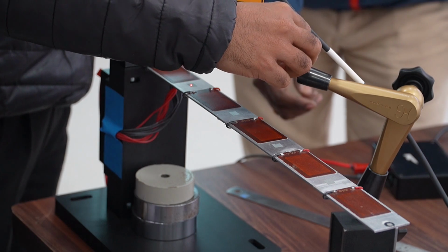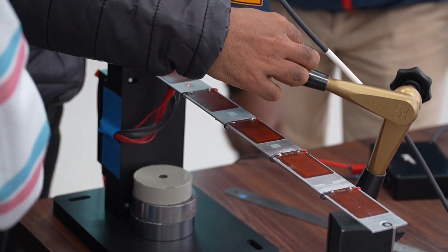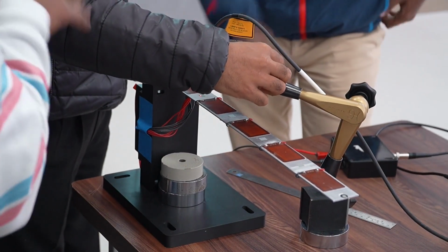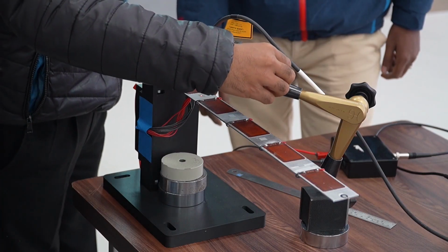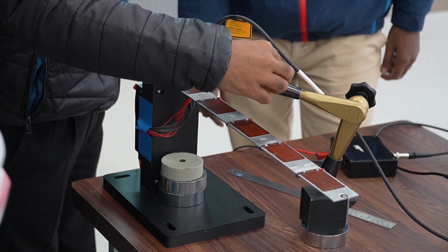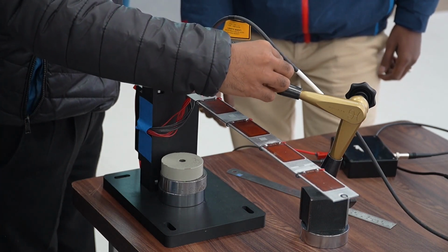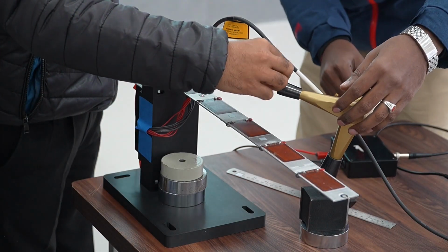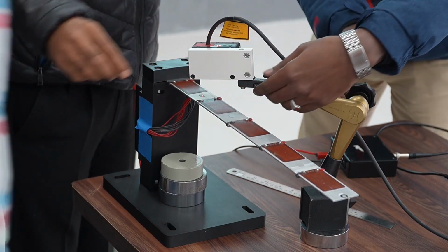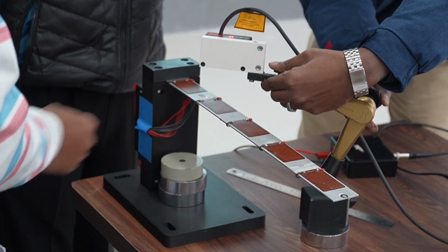How will you identify the second mode frequency? Yes, we need to use that. So excite the PZT, and the control voltage is given in the upper box. 20 volts, so 0.1 control volt. Okay, with a sine. Not DC, but a sine, a harmonic signal. Okay, go for it. Before you activate this, please ask.